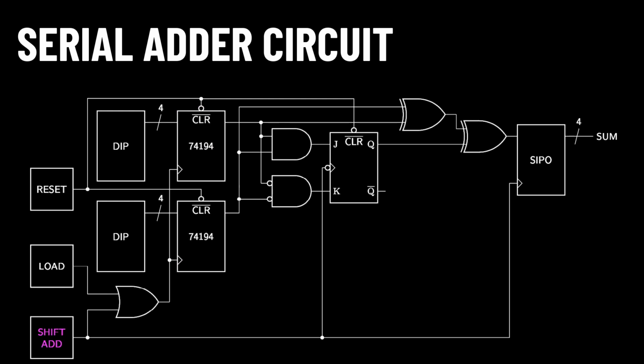Then, a separate push button can be used to sum each individual LSB in the register while simultaneously shifting data from the MSB to the LSB in the register, such that the next bit in line is available to sum on the next clock trigger.